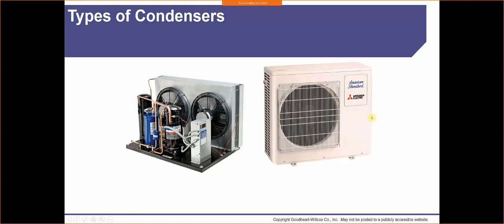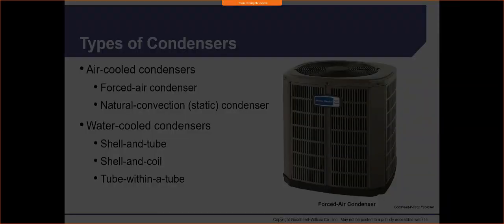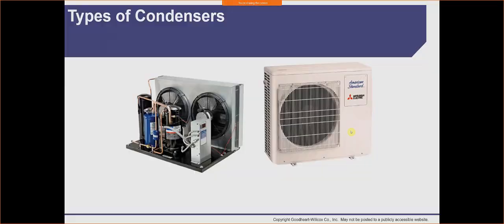So off to the right, what we've got here is a Mitsubishi condensing unit. A little bit of a different design than the traditional system in the back here, but it performs the same. The nice thing about these is that they can ramp up and ramp down, which means that if I have a cooling demand of 12,000 BTUs, but let's just say it's a lukewarm type of day where it's only maybe 75, but I want a little bit of cooling, on a traditional system I'm going to get all 12,000 BTUs for that space.